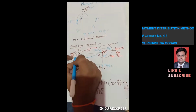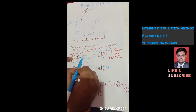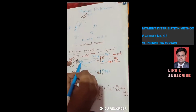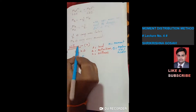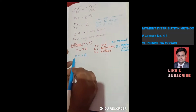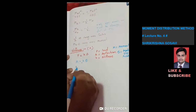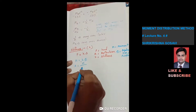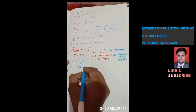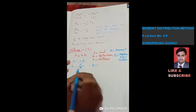What value of MA should be applied over here to get the unit angular displacement? That we will find out. Why do we want to calculate that? Because ultimately we want to calculate the stiffness. Looking at the equation M is equal to K into delta, I can modify this: K is equal to M by theta, since for M, theta is there.